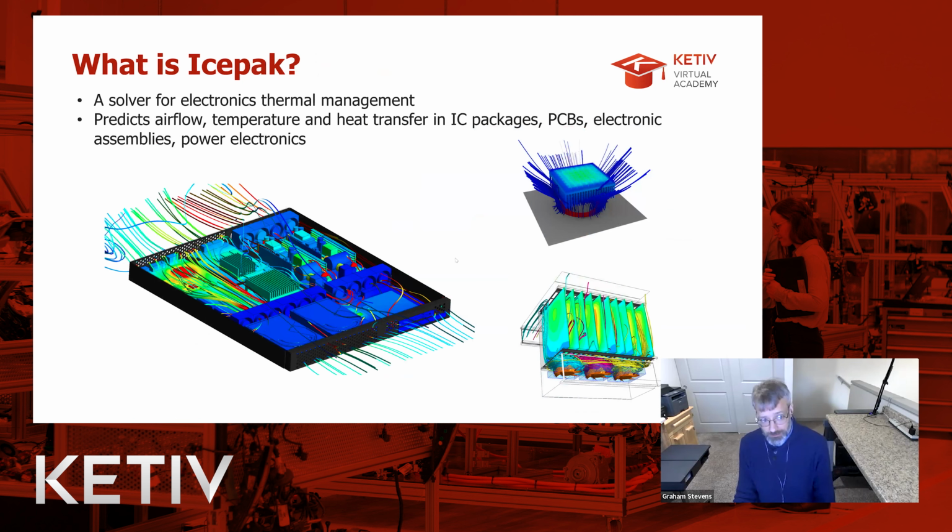So as I mentioned, IcePak is a solver for electronics thermal management. It's typically special purpose designed for this. I've got a package with boards, and I'm now trying to cool it, and I want to simulate both the airflow through this package as well as the conduction and/or radiation. And so it can handle all of those.